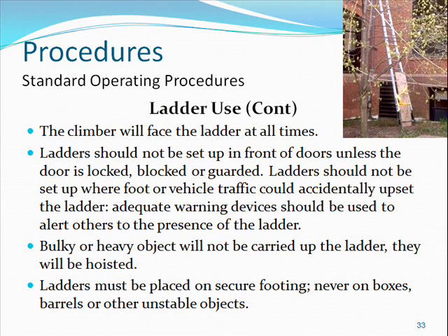Ladder use. The climber will face the ladder at all times. Ladders should not be set up in front of doors unless the door is locked, blocked, or guarded. Ladders should not be set up where foot or vehicle traffic could accidentally upset the ladder. Adequate warning devices should be used to alert others to the presence of the ladder. Bulky or heavy equipment will not be carried up the ladder. It will be hoisted. Ladders must be placed on secure footing, never on boxes, barrels, or any other unstable objects.